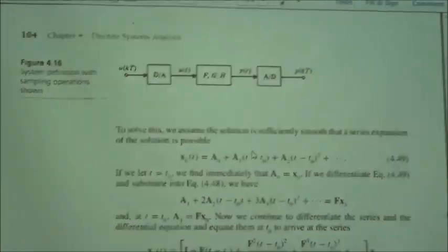In this lecture, we showed you two alternative ways of drawing simulation diagrams. In the controllable canonical diagram, the output of every delay term or every integrator, depending on which system you're looking at, is called a state variable. The inputs of them are going to be the expressions for the state equations, x1 k plus 1, or x1 dot, x2 dot, x2 k plus 1, and so forth.